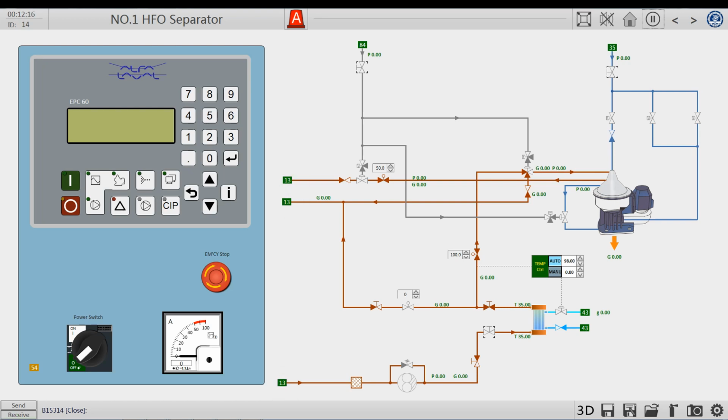In addition to preparing fuel, we also need to have compressed air ready. The compressed air comes from the compressed air system. Relevant valves also need to be opened. Freshwater comes from the daily freshwater system. Valves also need to be ready and open.